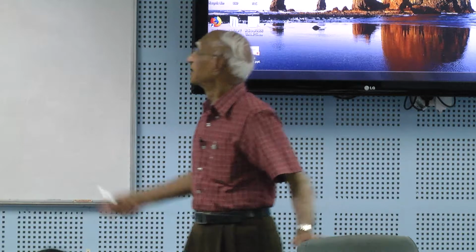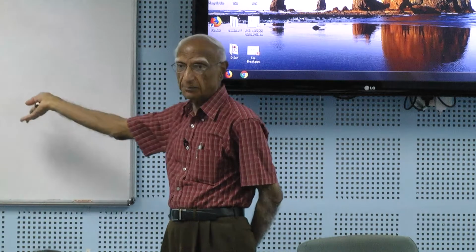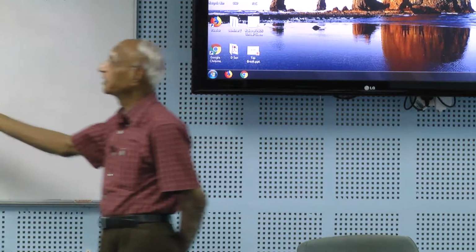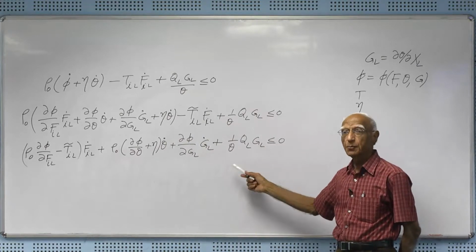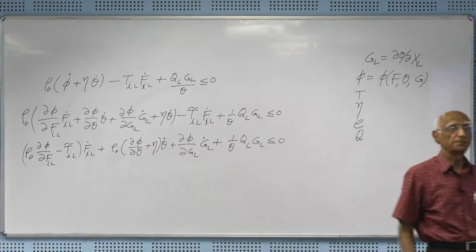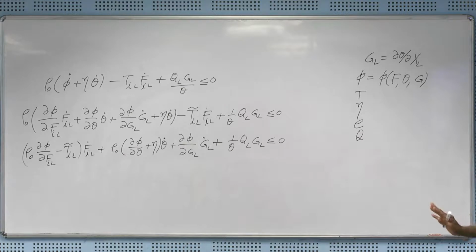So for a thermoelastic material, this being the definition of a thermoelastic material, the reduced entropy inequality is this one. It must be satisfied for all solutions of the governing equations. What I said in the morning was that only those solutions of the governing equations are admissible that satisfy this equation.